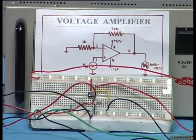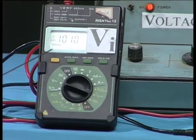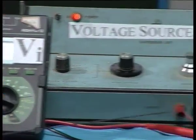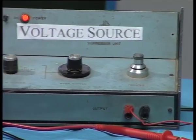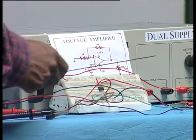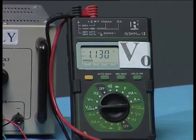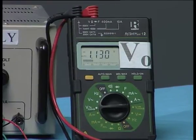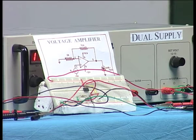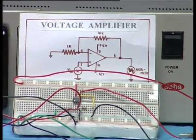Now if you look at the dial here, I am sure you are able to see that it is about 100 millivolts that is obtained from this voltage source. It is connected in parallel to the voltage source at the breadboard, and therefore it reads 100 millivolt. After amplification you see 1.13 here. So the gain is 1 plus R2 by R1, that is 11, and therefore 11 times 100 millivolt is 1.1 volt. That is what you are getting here, which is what we also got in the actual simulation.